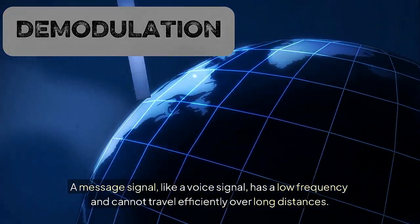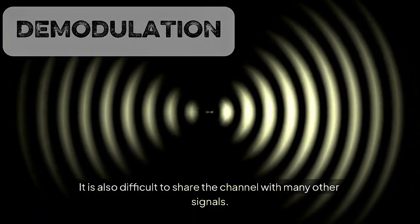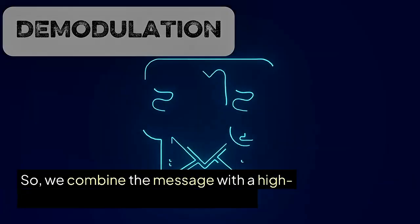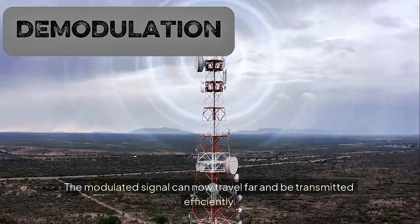Why demodulation is needed. A message signal, like a voice signal, has a low frequency and cannot travel efficiently over long distances. It is also difficult to share the channel with many other signals. So, we combine the message with a high-frequency carrier using modulation. The modulated signal can now travel far and be transmitted efficiently.